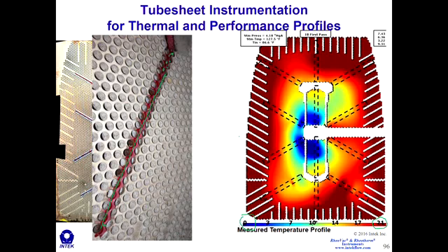We use a program to interpolate all of these measurements, using a model that we have to interpolate between all of these different points. And this is the temperature map for this particular condenser. You can see right away, the way I like to look at these plots isn't really in the temperature mode. We can see here that there's 0 temperature rise here, there's about 14 degrees temperature rise here.